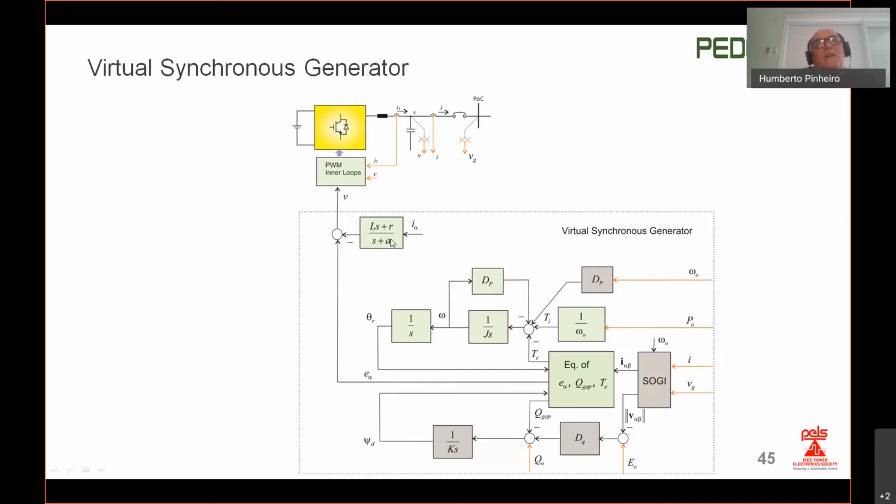We add an additional pole here since this transfer function is non-causal. In order to make it causal, we introduce an additional pole in this transfer function that will affect the behavior of this reactance in the high frequency end, where the droop control no longer has an effect.